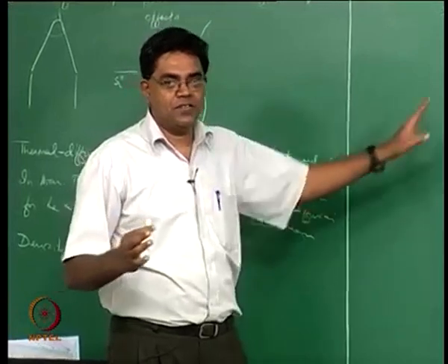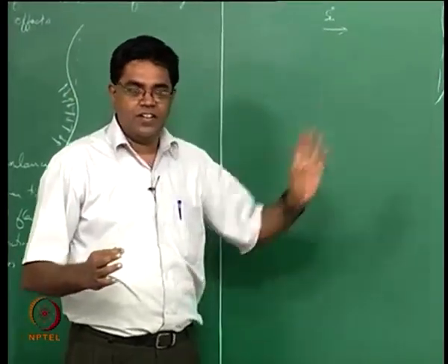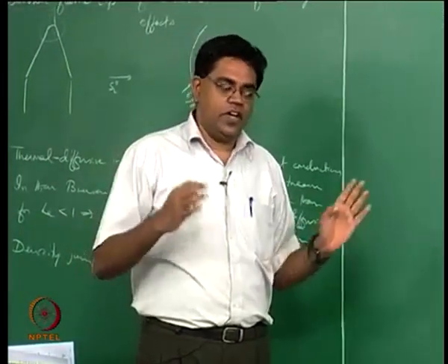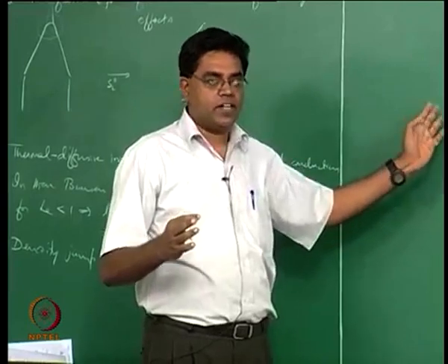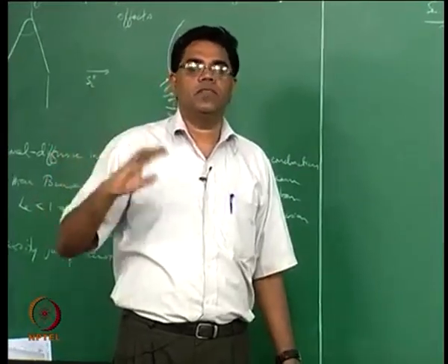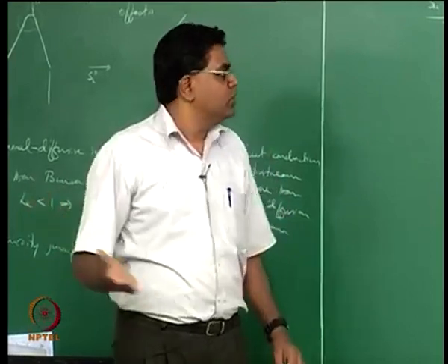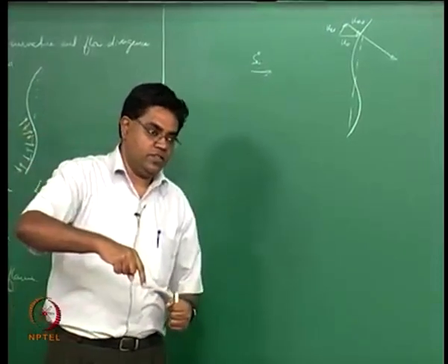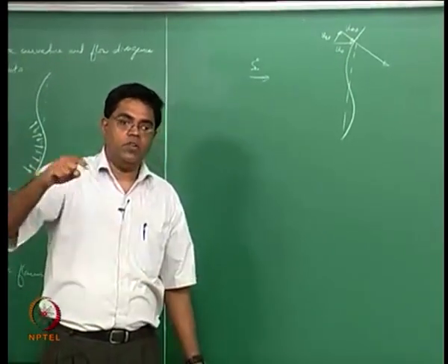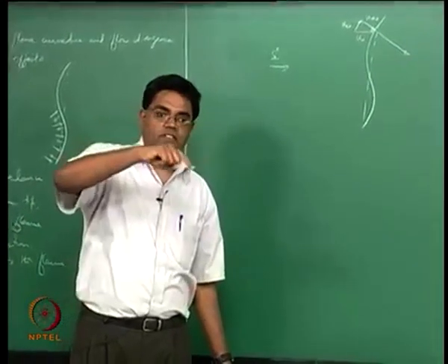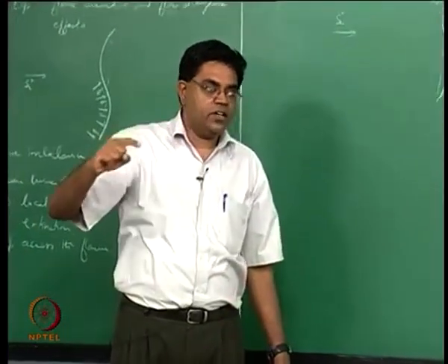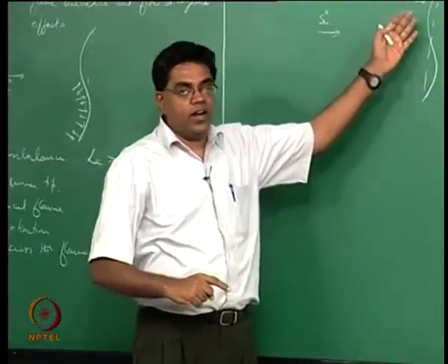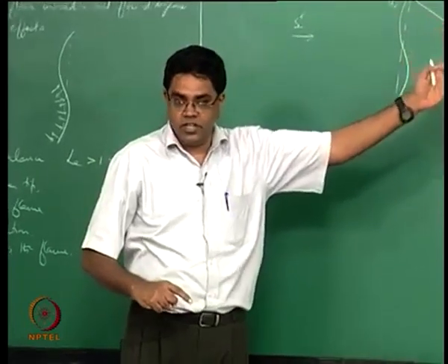Okay, think in terms of factors of 3 or 300 for the sake of simplicity, or 3000. So you are now talking about a factor that's somewhere between 7 to 10 times more. So this has to be significant, and the density correspondingly decreases. So P equals rho RT, and as T increases rho has to decrease, and then rho naught U naught is equal to rho infinity U infinity, or more specifically in this case rho naught Un naught should be equal to rho infinity Un infinity.